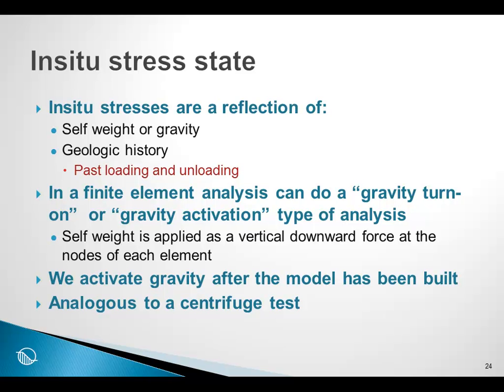The reason for this is that in situ stresses are a reflection of the self-weight or gravity. That's quite easy to handle, but the in situ stresses are also related to the geologic history. That is the past loading and unloading, and this component of the memory of the soil is rather difficult to establish sometimes, although we can approximate it.